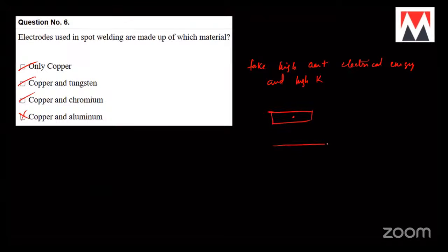Suppose I have a wire like this that I want to join. Generally, thermocouples are joined like this. In a thermocouple you have two wires like this, a K-type thermocouple. So many thermocouples are there, very high temperature thermocouples, right? You have two different wires, two different terminals. These two terminals will give you a difference in voltage. This voltage will tell you what the temperature difference is. So for this, you stick them together like this. This is spot welded actually.